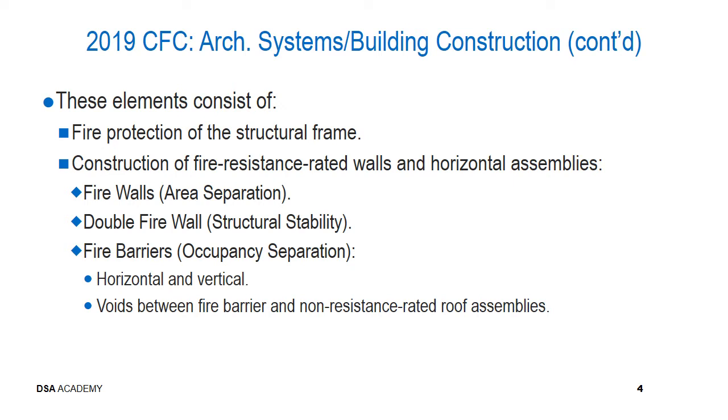706.6 and 706.6.2 of the Building Code also note that firewalls in buildings with sloped roofs greater than 2 in 12 must extend beyond the roof surface to a height equal to the height of the roof located 4 feet from the firewall plus 30 inches. Verify compliance with the plan details.